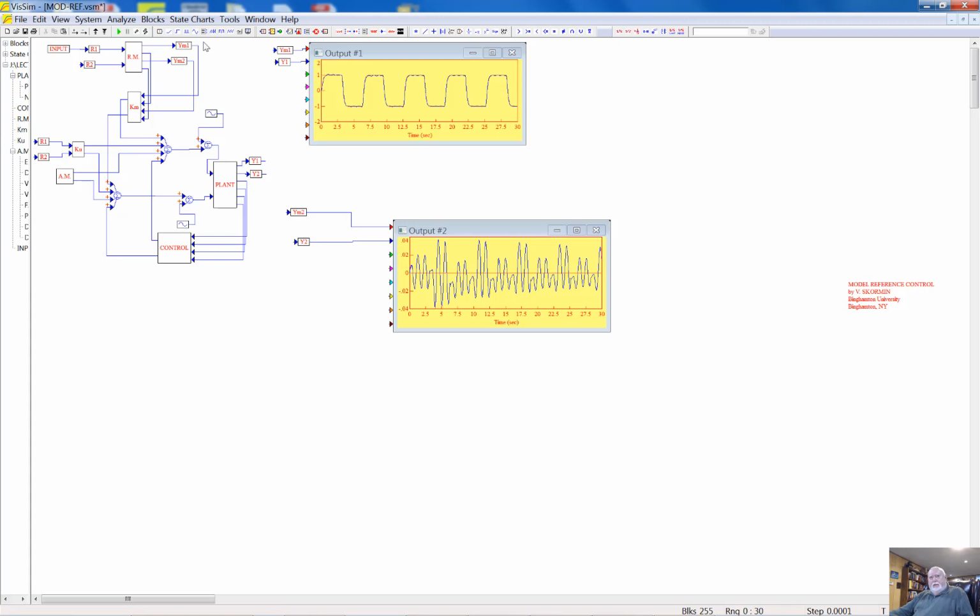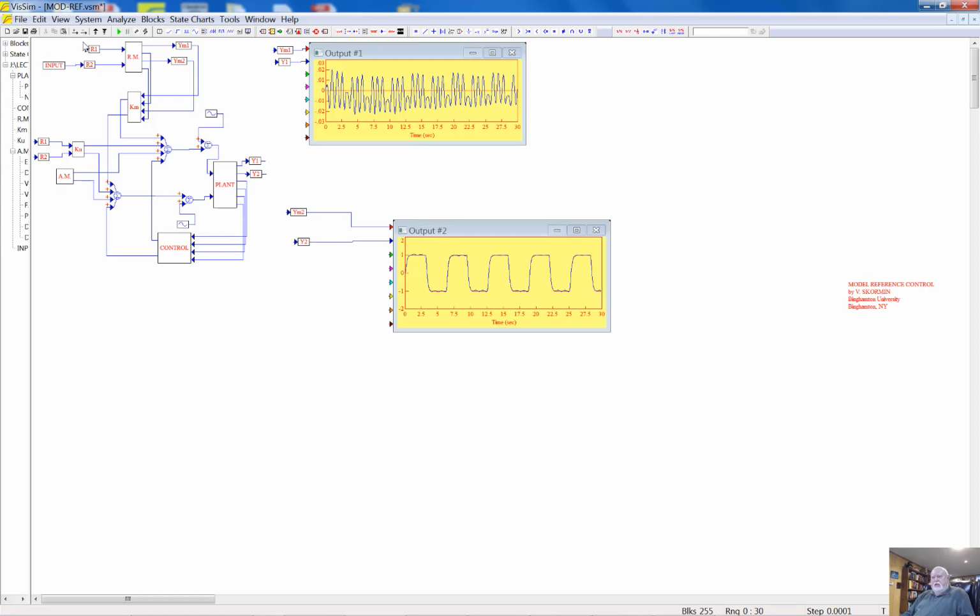Anyway, now what will happen if input is applied to the input number 2? System, and go. Yeah, the same situation happens. The disturbance affects the response of the control plant, but the effect is very, very small. You may or may not see this ripple. As far as the response in the output number 1, it is very small by absolute value, and it converges to 0.